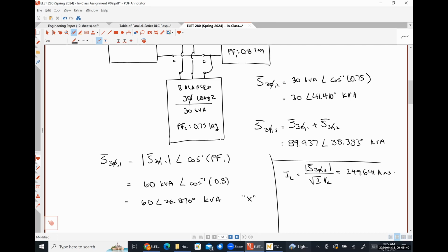So I want to be clear here. Because we were only interested in the magnitude, that's why I chose to use my apparent power relationship, because apparent power only depends on the magnitudes. If I wanted to know the actual value of the current as a phasor, I would have used the full complex power and effectively done this thing, but taken the conjugate.